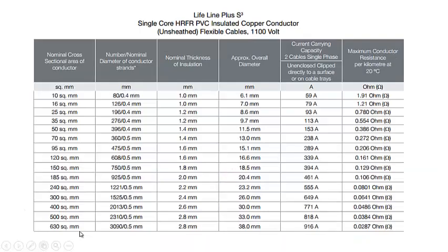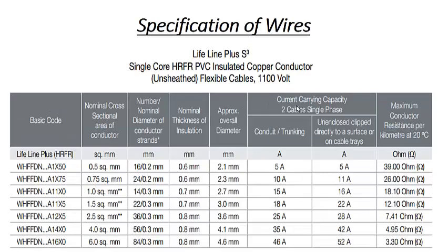But if the load increases, here we have 10 square mm, and its current rating is 59 amperes. This shows only the unenclosed value, outside the home, because when you use it inside the home, the values above will suffice, since for underground cabling or fitting inside walls, the load will not go beyond 46 amperes.